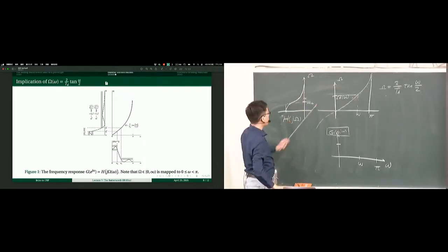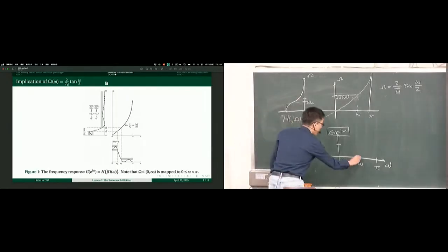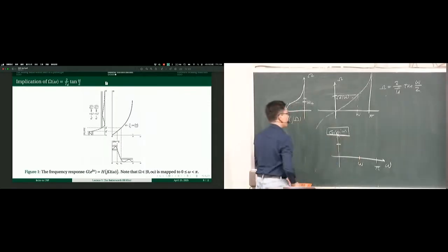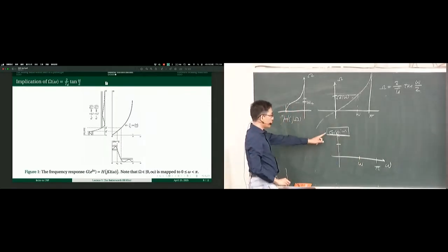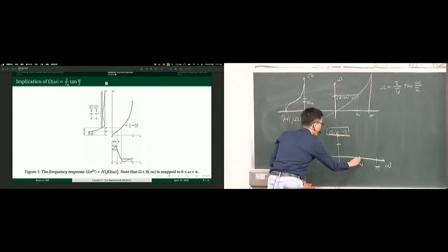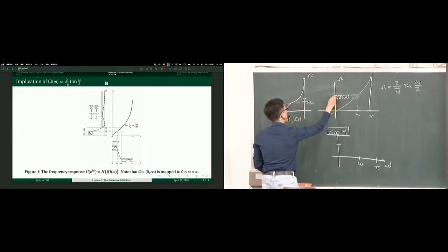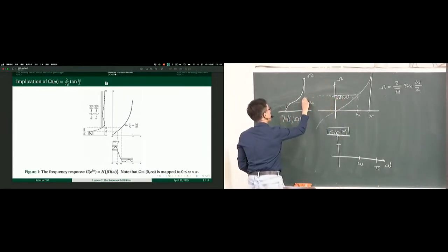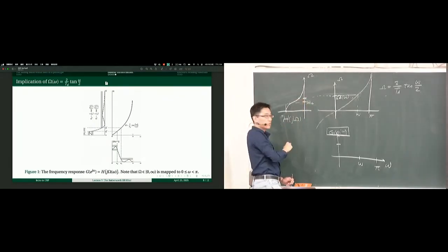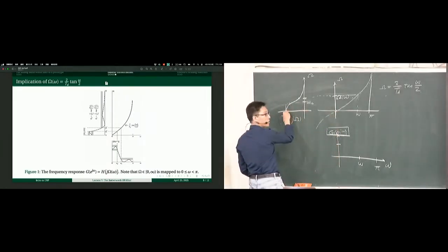And if you just plot it by turning it 90 degrees counterclockwise, then to evaluate the resulting frequency response now as a function of small omega, just first choose any random omega right here and find the corresponding big omega, and then the big omega right here goes here, right? And then what is this? This is a gain. Is that clear? So it's DC, and the gain is 1.